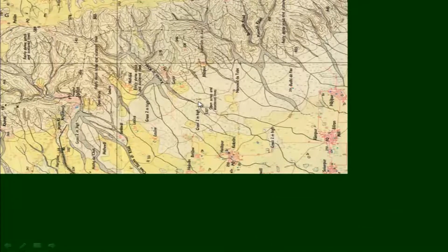And the contour interval, what you see here is around 240, then this one is less than that, and then you have this one over here. So the contours are widely spaced. If you move towards this side, this marks the closely spaced contours. So, this indicates that this is the hilly terrain and this is more or less a flat surface.